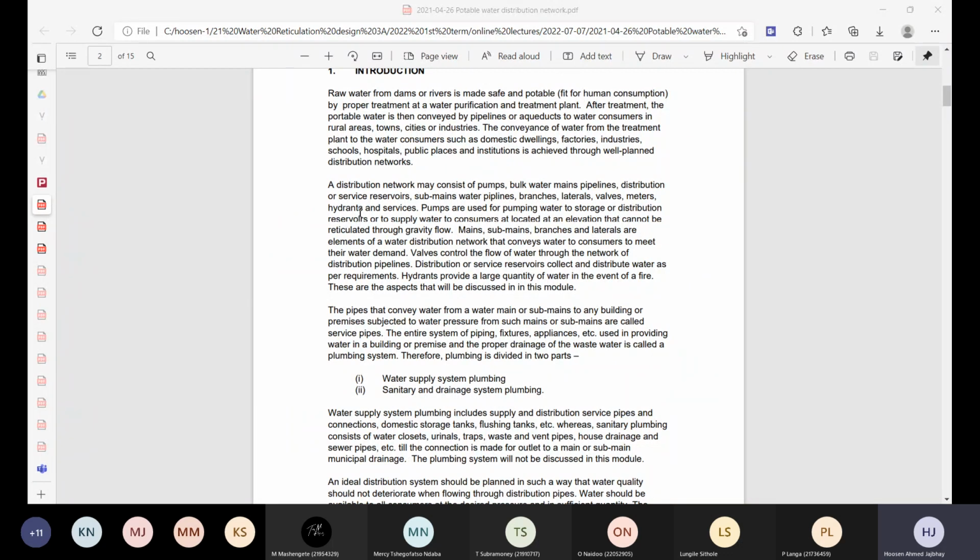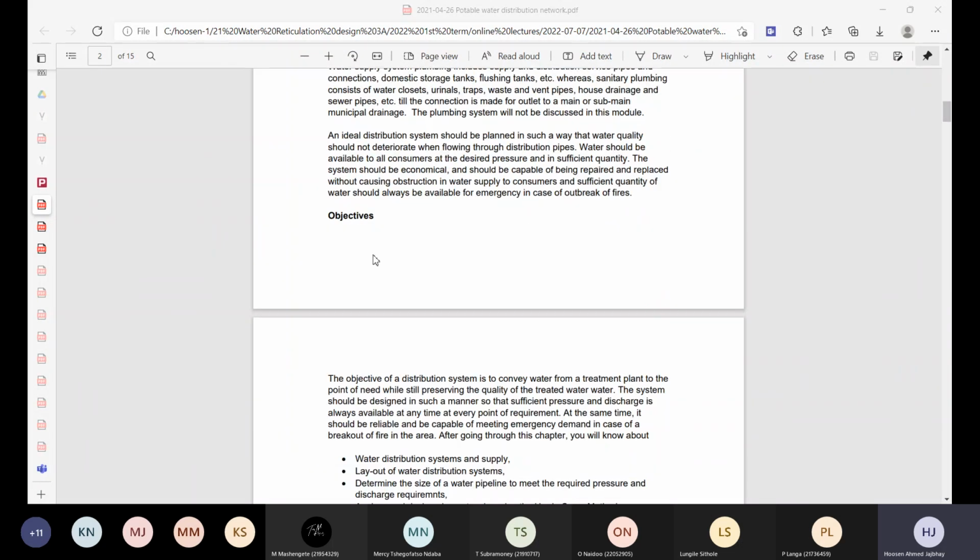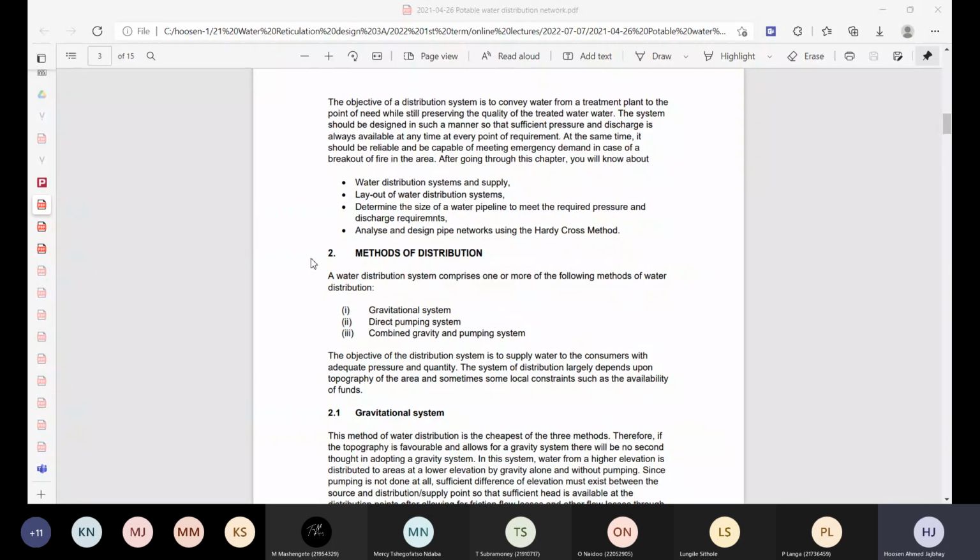In the South African context, generally our dams are built upstream because the land slopes towards the coastline. So if our dams are upstream, then we can achieve gravitational flow in terms of our main distribution, and we can avoid pumps. I'll talk about pump systems just now. You can read through the introduction there, it's all written there for you to read.